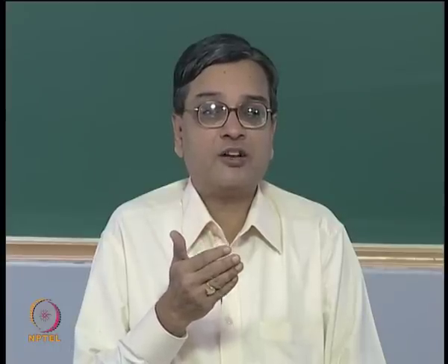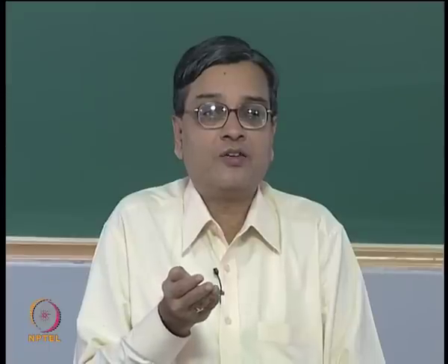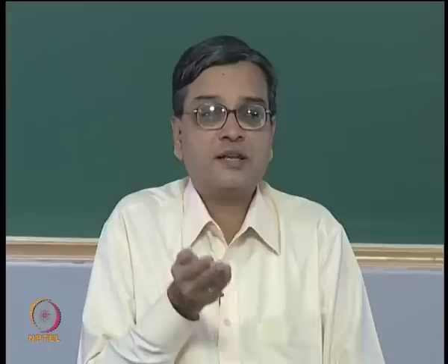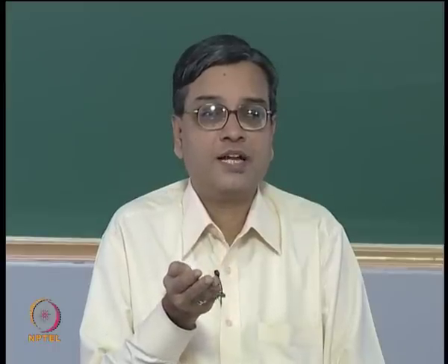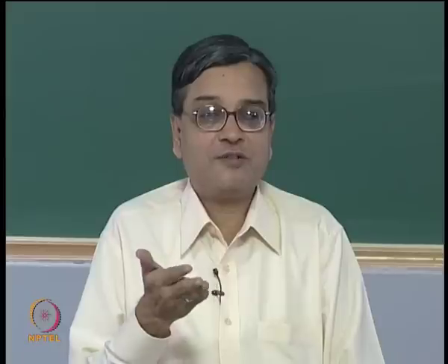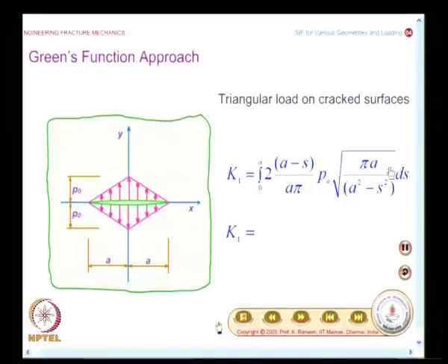If you had looked at when we wanted to find the energy release rate based on displacement of crack faces, we had a discussion that the crack is opened by a pressure which is equal to sigma, and we gave some expression for the value of k, and we would see what kind of expression for k we would get. So, both the expressions are important, and what you will find is, in each of these cases the integral will be different.